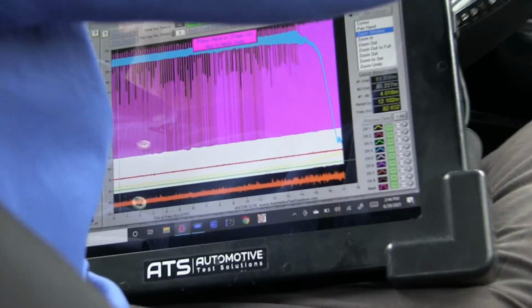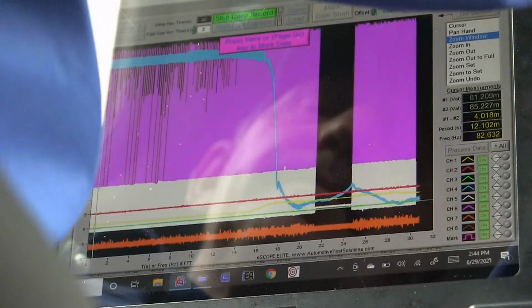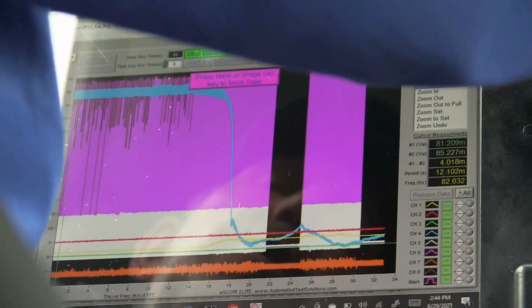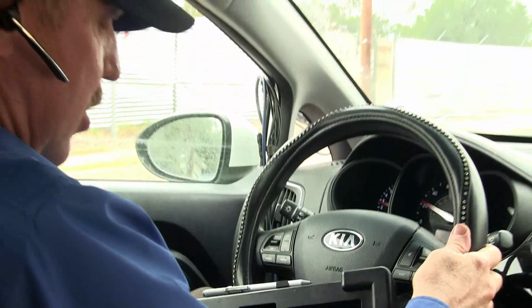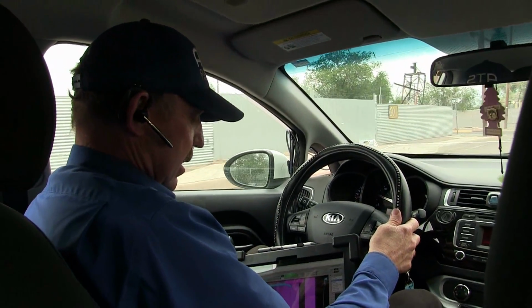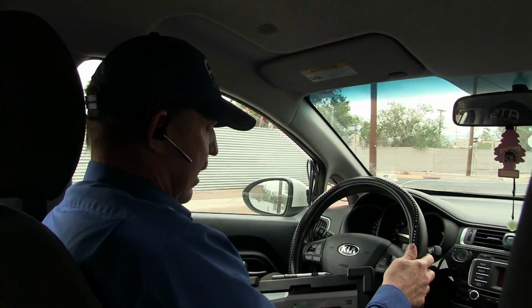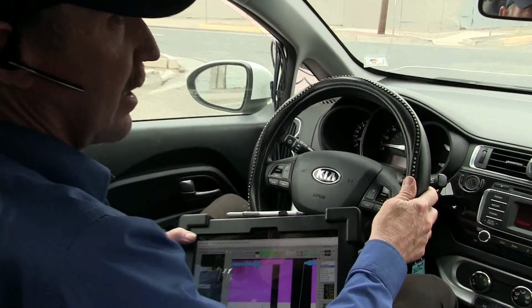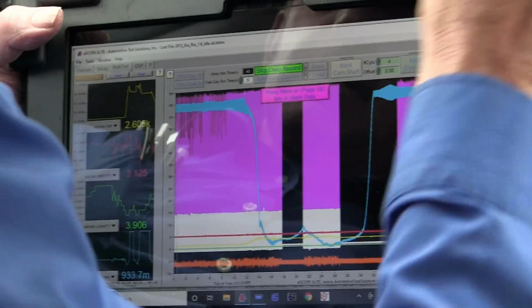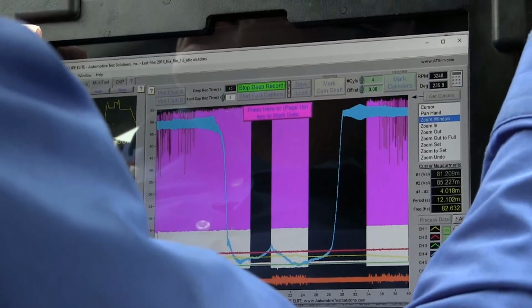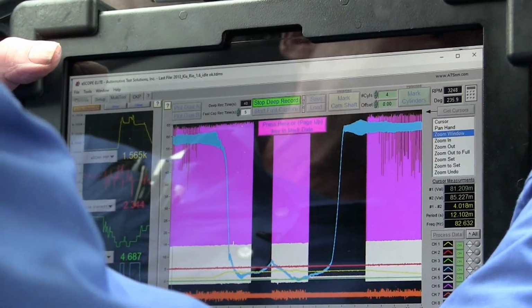So it fails when we're in it hard. It didn't fail. I was in it. Wow, look at the pressure. The low pressure fell totally away. Now, I didn't feel the car cut out, but that low pressure is definitely falling away. So let's get the high pressure to fall away and get the car to cut out, like what we saw before.